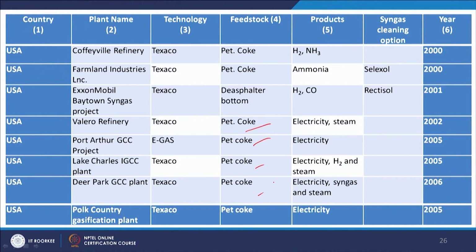So, here also you see all pet coke. Pet coke has been widely used for the production of electricity, but sponge coke and shot coke types are used, while needle coke is not processed through this route, as it has better applications as electrode. So, in this part we have seen how the vacuum residue can be converted to different liquid products, and the solid part also, that will have more value than the conventional petroleum coke.